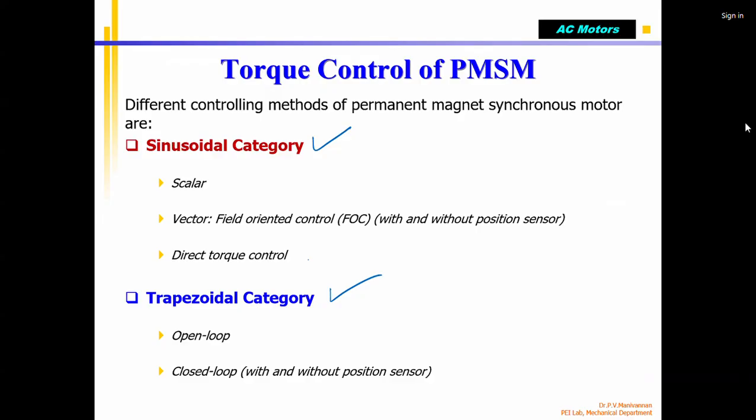And the rotor also produces a back EMF because the distributed coil is there. In that case, if your coils are excited, or permanent magnet motor excited sinusoidal, you get sinusoidal back EMF. You have 3 types of motor control, speed control. One is called scalar type, other called vector field type, FOC, field oriented control. Third one is called direct torque control.